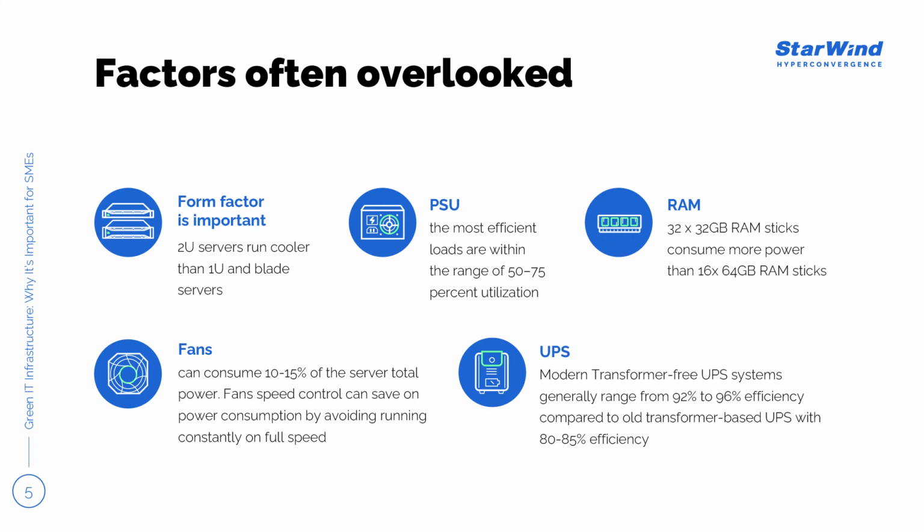So if the UPS is operating at 100% capacity, meaning drawing its full wattage, of course it will run as efficiently as its rating implies. But if the UPS is operating at a lower capacity, as almost all do, its efficiency will be lower. As an example, we can take a UPS running at 20 or 25% load. It might only be able to provide a lower efficiency, for example, of around 80%.